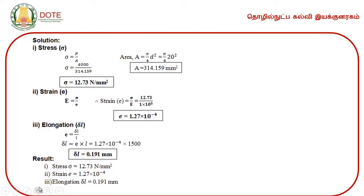First we will find the stress value. Stress is given by the formula P by A. What is P? Axial load divided by area resisting the applied load. Stress is given by load by area. Load is nothing but applied load. Here it is 4000 Newton divided by the area. Area is given by pi by 4 d square.